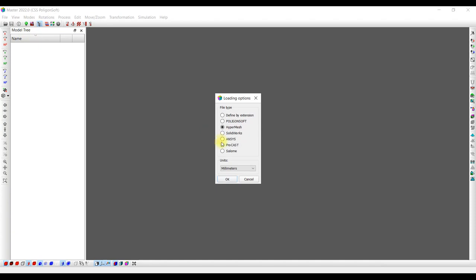Many mesh files of different formats are suitable for loading the finite element model. You can follow the program to define the default files, but it will set units of measurement only in meters. What are the units of measurement here? In general, mesh generators work without measurement systems. That is, there are some coordinates there, but in order for us to understand the dimensions, we need to put units. Usually we put millimeters.